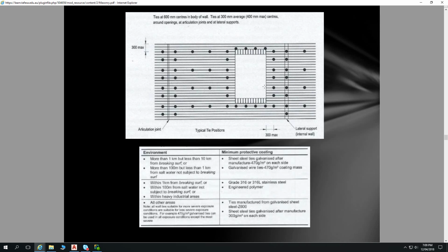You need to have expansion and contraction joints at ever so often. You can pull those two together and then use the minimum distance of the spacing of those and call it a brick control joint, and that takes care of both. Basically what it is, it's where we have a 10mm gap in our brickwork that goes from floor to ceiling.